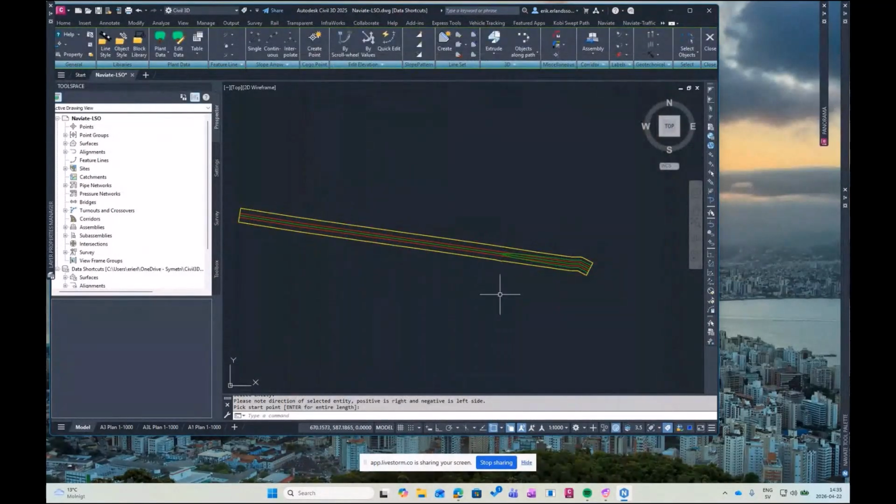So this line set template, what it does, similar to when I create the pipe, creates a draped line that is connected to the surface, and then an offset one down under, and then it creates 2 datum lines, one to the left and one to the right for the bottom, and then with a slope 1 to 1 up to the surface again.